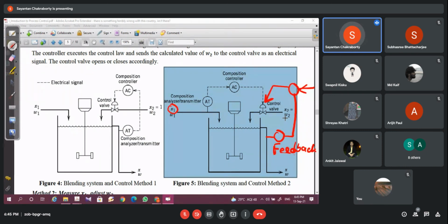So in most control systems, whenever we apply a feed-forward control, we never rely completely on that. Feedback control is also provided as a supervisory one. You have to compensate the entire system, not only using feed-forward or feedback alone. So the feed-forward and feedback combination is the way to go to solve this problem.